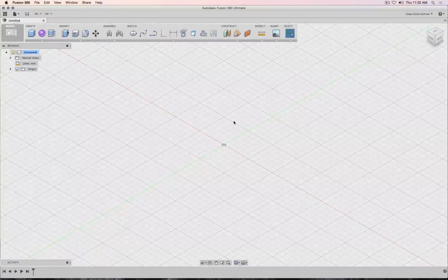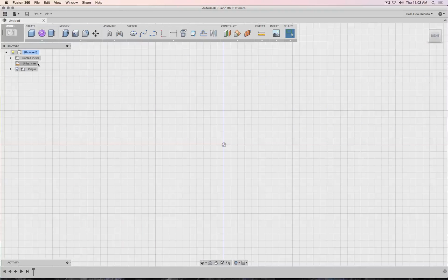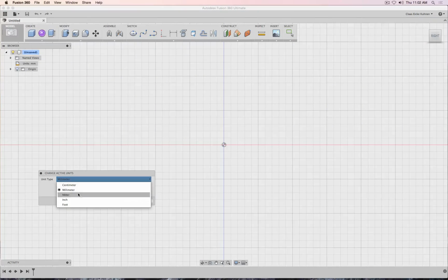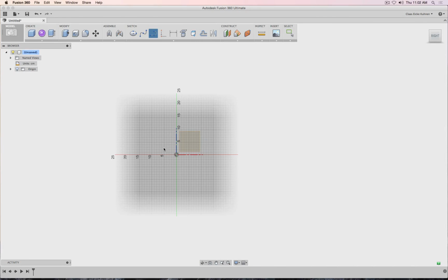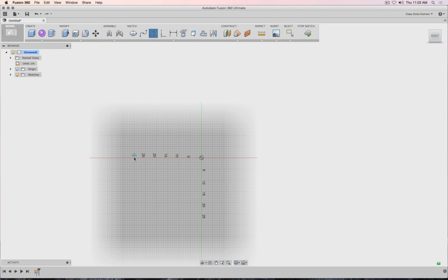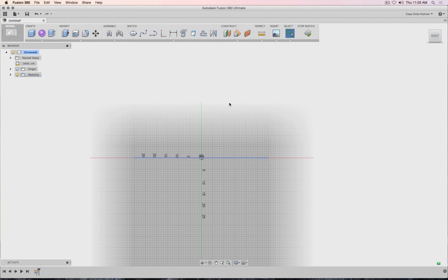Let's take a look at how we can create a chair that's built out of a bent plywood shell, and that one is resting on a pipe frame. I go to a site, I set everything to centimeters, create a sketch, and actually before I do anything, I'm going to create myself a nice flat, kind of like an orthographic cross-section view of my design. So this is, for example, 60 centimeters, kind of like the front and the back end of my pipe legs.